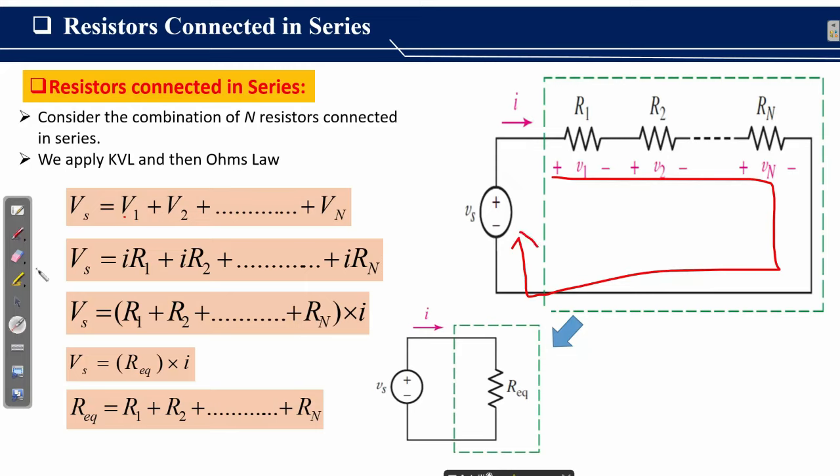like this. So how do we know that resistors R1, R2 and Rn are connected in series? For this, we take first the two resistors R1 and R2 and consider these two resistors are connected to this common point or node N. So if resistors R1 and R2 are only connected to this common point N, and if no other circuit element is connected to this common point N, then resistors R1 and R2 are said to be connected in series.